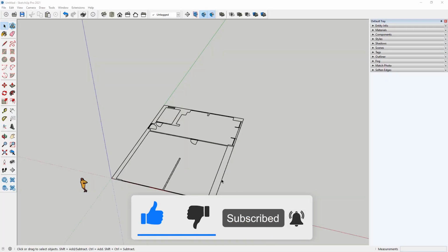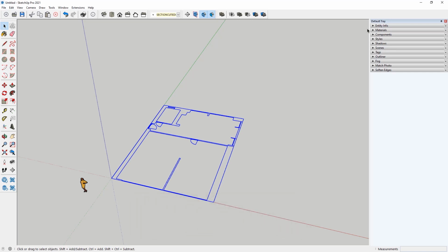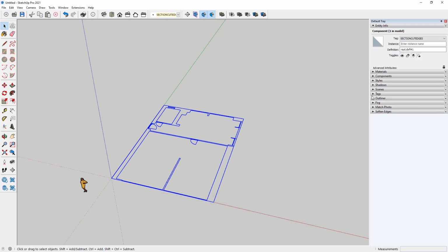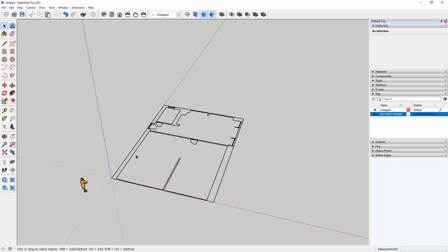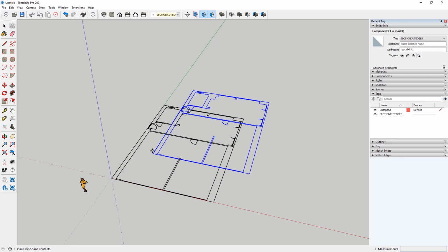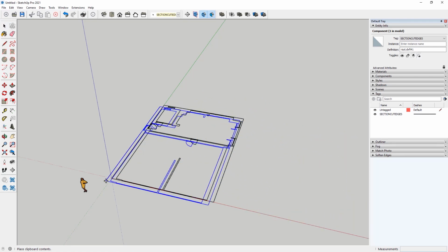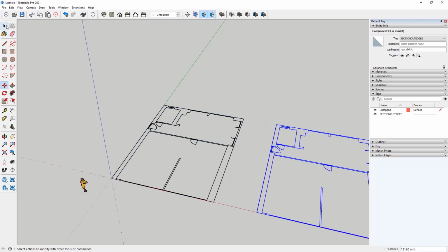So in this class we are going to start to draw the walls, but before that I will go to the tags bookmark and add the new tags. Right now the section is under section tags, so if you turn it off, you will also see that the view from the main view will also disappear. Unfortunately, I would like to have it all the time, so I can very fast go back and see it. So I will just copy it and paste it into the zero point of the axis, and then I will move it to the right side.